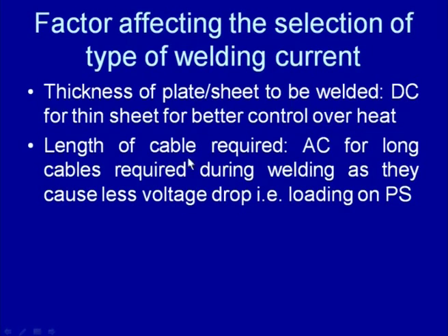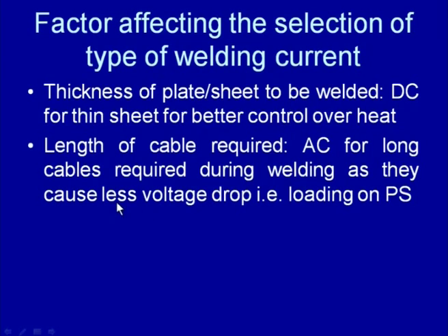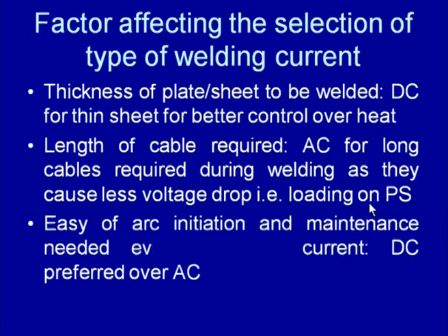Similarly, the length of the cable to be used during the welding: if very long cables are to be used, then AC is preferred because it causes less voltage drop and so less loading on the power source. This in turn decreases the cost associated with the power consumption.